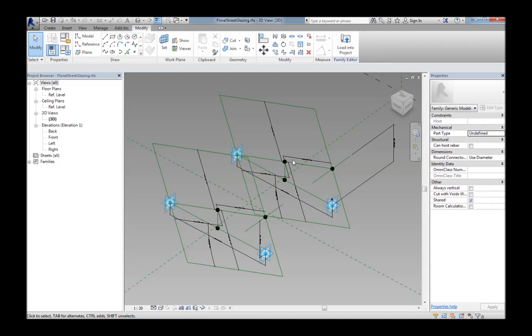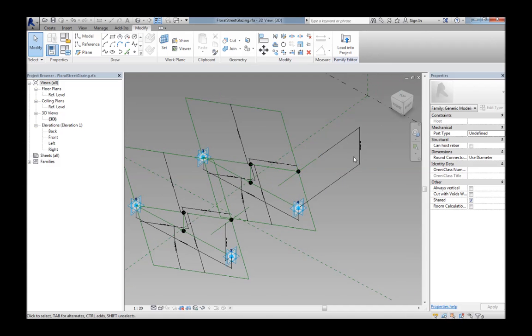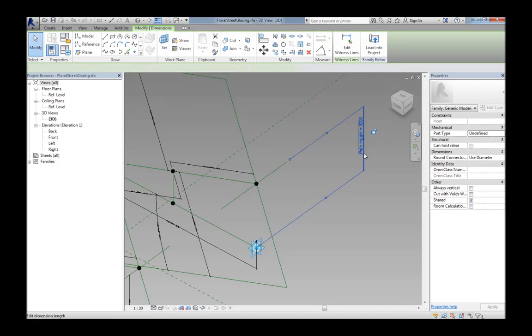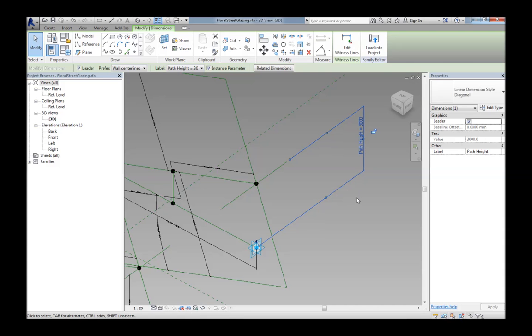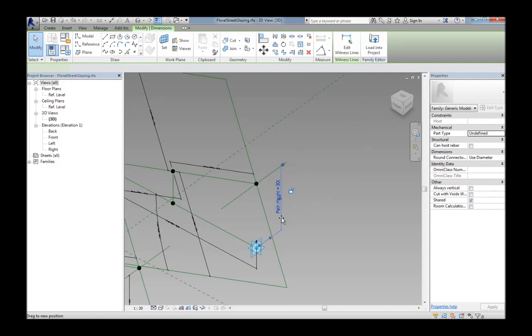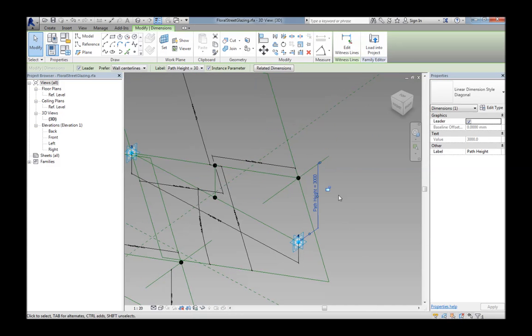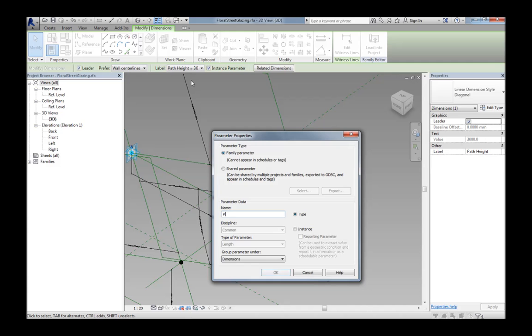so the only real thing then, now that you have the same lines, the same dimensions, is you need to create new parameters, a second set of parameters basically for the second profile. So that's what we're doing here now.